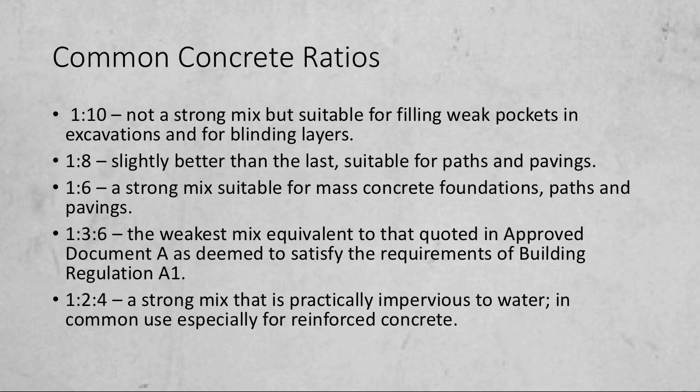And you have the 1 to 2 to 4, a strong mix that is practically impervious to water, in common use especially for reinforced concrete, and that's the mix we tend to use typically in our households right across Jamaica as standard for most construction. I will not say all, most.